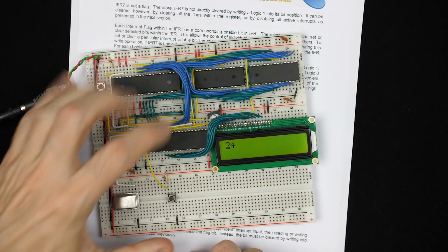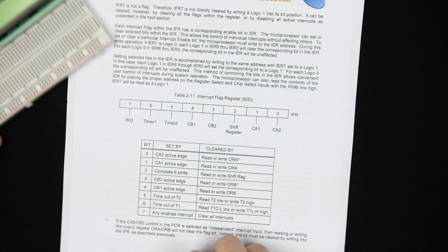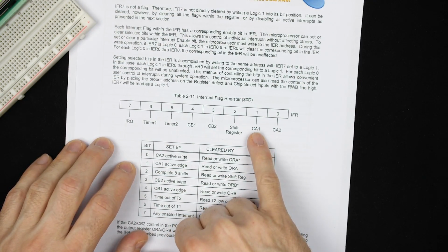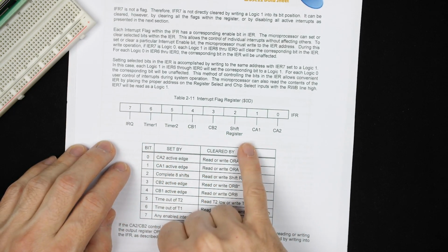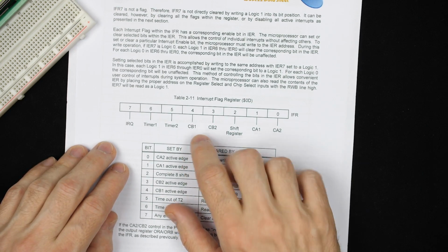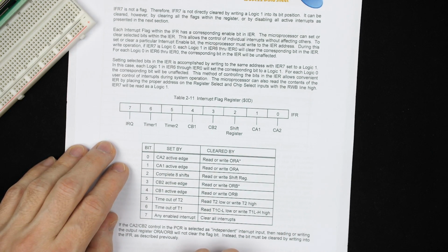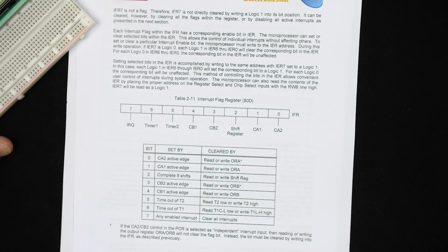But even in this case where we have a single chip, the interrupt still could be caused by multiple sources. In our case, we know it's not because we only have one thing enabled that'll cause it. But if we had some timers set up or some other things, then we would need to read this interrupt flag register to figure out what actually triggered the particular interrupt that we're handling. And perhaps in a future video, I can talk more about how these timers work to show a more concrete example of that.